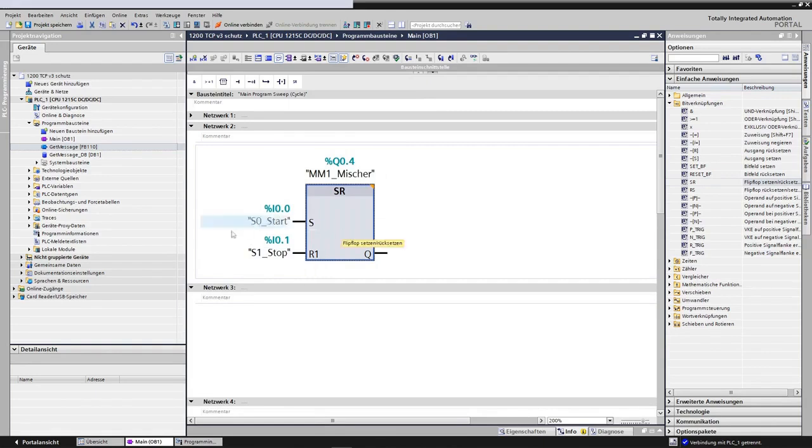So the simulation gives us a normally closed signal when we press the stop button. This means that in the idle state, there is a 0 here. That is not entirely correct. A stop button should always be implemented as a normally open contact, and we should normally measure a permanent 1 signal here. When it is activated, this signal is interrupted, and then we would also need to place a negation, an inverter, here, so that this input is inverted or flipped.